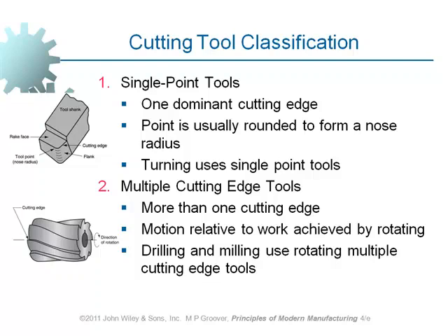Because when we've got a number of cutting edges, it does distribute the wear which is being applied to the cutting edge, and as a consequence, your cutting tool lasts longer because there are a number of cutting edges taking the cut at the same time. And you will have less frequent tool changes for the operation. And of course, when there is only one, you will have more frequent tool changes, which is not actually of interest.